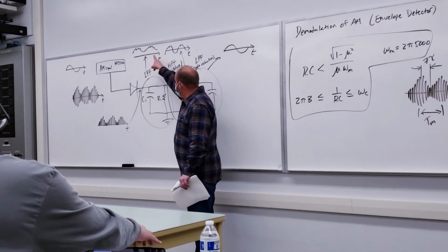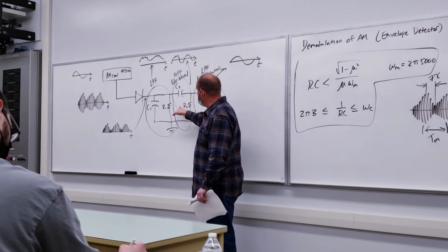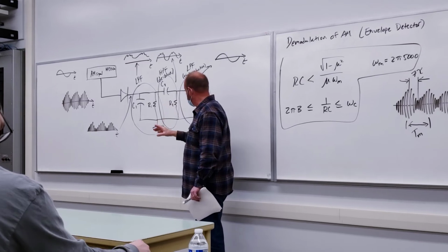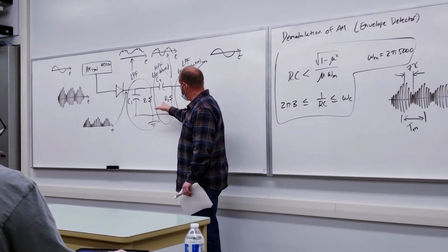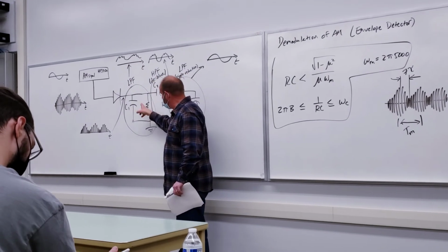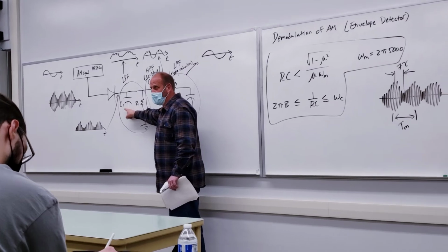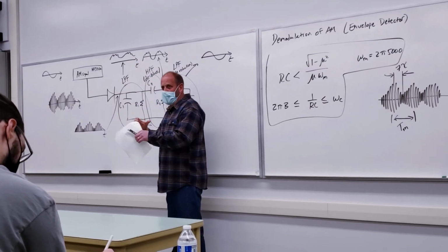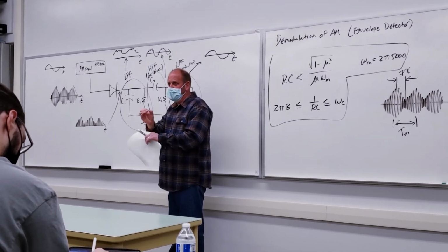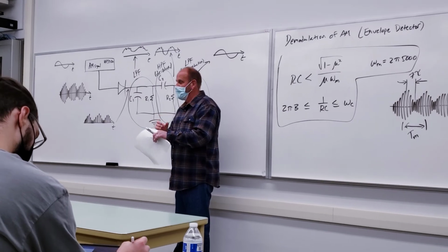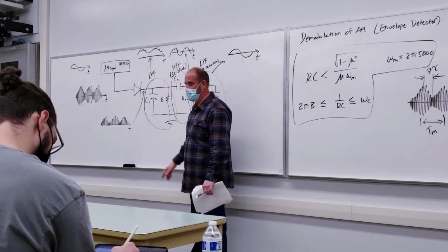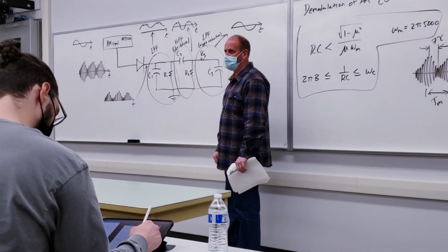So once you've got that picture, this is a simple stage because you just want to eliminate that spike sitting there at 0 frequency. The only thing you have to worry about is that you've worked real hard to get that nice picture. If you have a capacitor that's too close in value to C1, you can mess up your picture. They interact. It's like a pole-zero plot where you've got two poles right on top of each other. So make C2 about an order of magnitude bigger or smaller than C1, and then that should be okay.